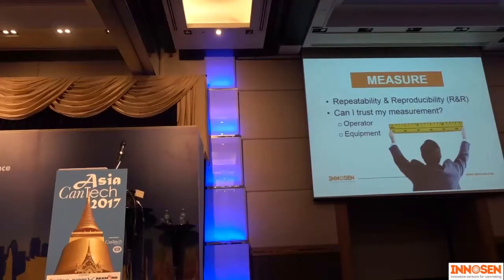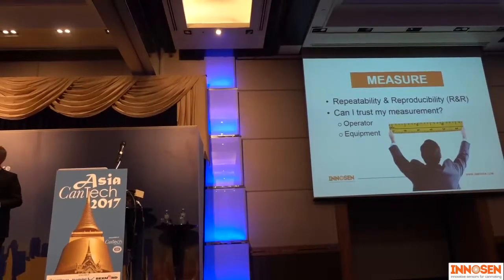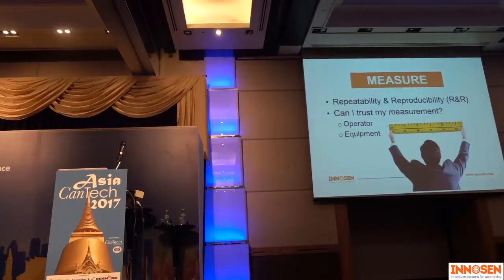Every time wrong. Well, that's of course not very logical. The coating machine doesn't know that there is a shift change, so it should not always change when the shift changes. This was an example of a gauge that they used to measure the sheets with that was not very reliable. When one person measured, it was okay. When the second person, a few minutes later, measures, it was always wrong.